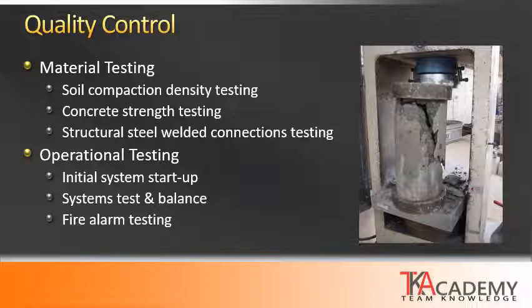Operational testing, sometimes this is put on the general contractor to do, but again, it's always best to do it as a third party. Some of the items that can be included in operational testing are the initial system startup, the test and balance of the systems, and fire alarm testing.